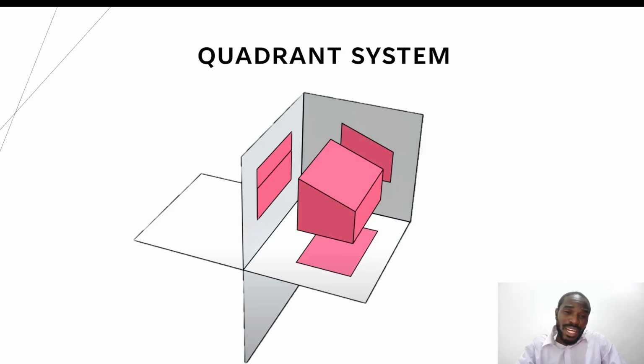So if you're going to draw a line, that line should meet, okay, I don't know whether you would see my cursor here now. If you can see my cursor, that's fine. If not, it's all right. So you can draw in projection. You want to follow this line until it gets to that plane. Now the line that you're going to draw in projecting this line or this vertex to that point will have to meet that plane at 90 degrees.